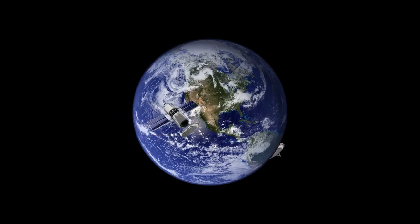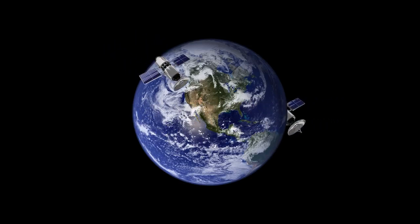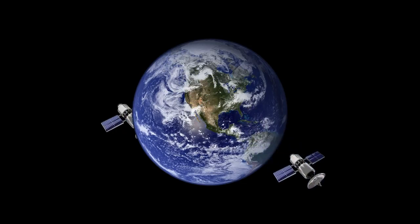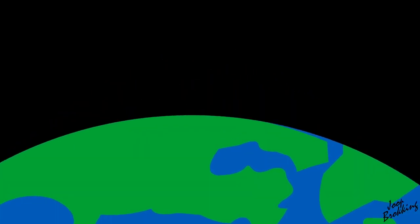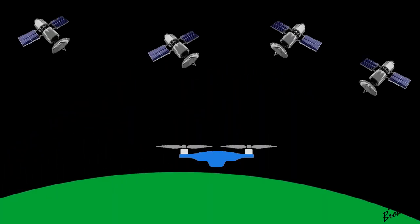A GPS module has the ability to receive these signals, and based on the travel time of the signals, it can calculate the distance between the receiver and the satellites. When there are 4 or more satellites in view, the GPS module uses these distances and the position of the satellites in the sky to calculate the latitude and longitude. It can calculate a lot more, but for now we will only focus on the latitude and longitude.